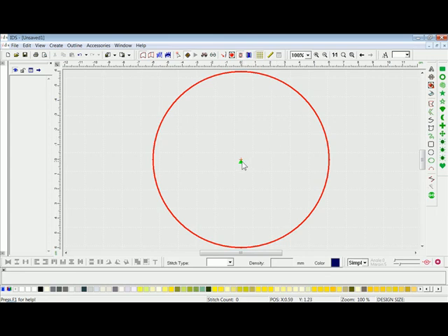We can also change the way that our grid is lining up on our design by going up to the upper left-hand corner where our two ruler bars meet. Where our two ruler bars meet, there is a gray box, and if we left-click, hold and drag on that gray box, bring that into screen, we can see we have two meeting lines. One is a horizontal and one is a vertical. If I'd like my grid to line up with that center point, I will place my cursor over that design center, let go of my left click, and my grid will shift to that point.